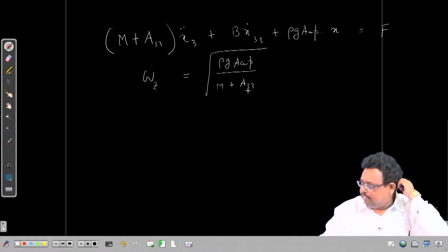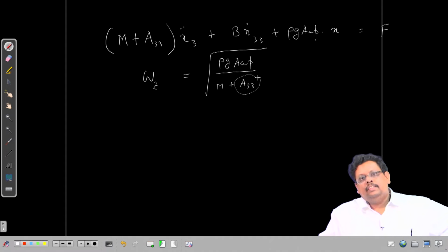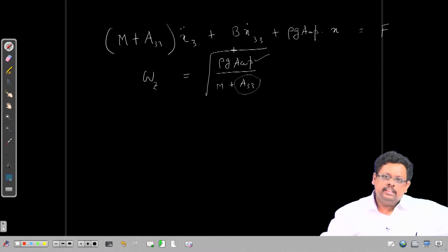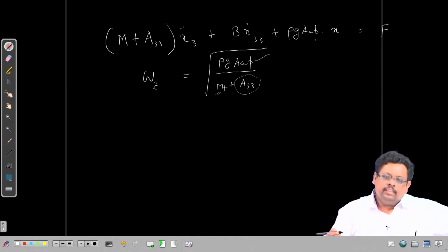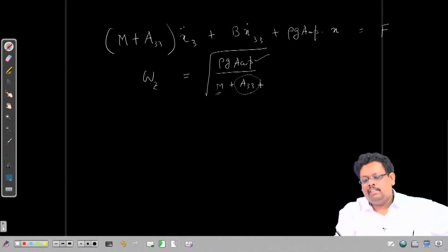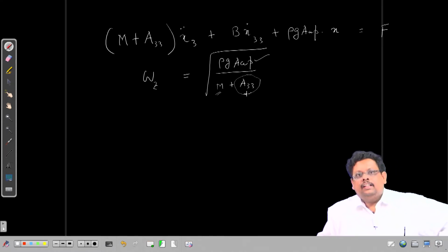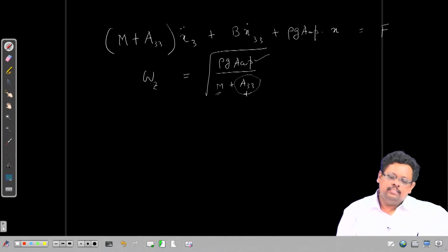Now, definitely in this numerical ship hydrodynamics class, we are going to discuss how we get this heave added mass A33. Suppose, however, in the first shot somebody asks you how to estimate the natural frequency for heave. A_WP is a geometry property, of course, rho is the density, g you can approximate as 10 or 9.81, whatever. The mass m you know. The only thing coming from the hydrodynamic side is basically the term A33. Now, ideally speaking, for engineers, how do we go about getting a realistic estimation?